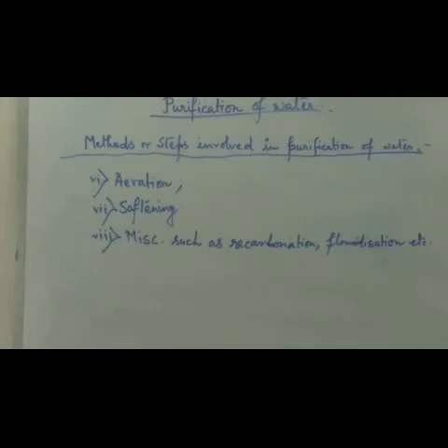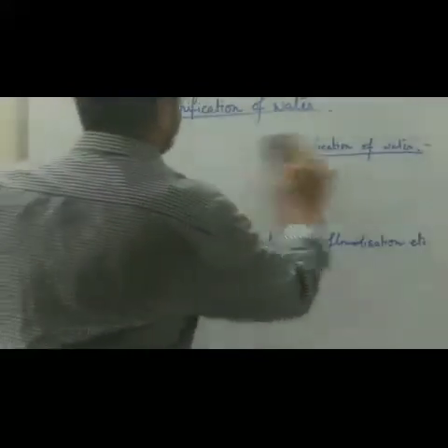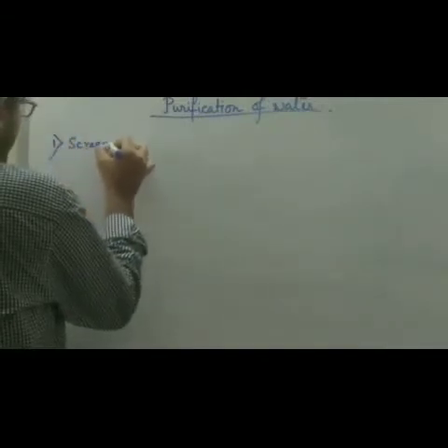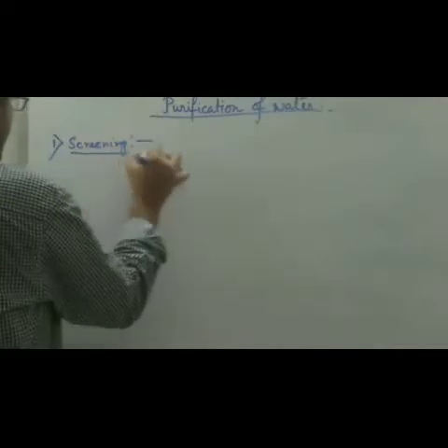So first of all we will discuss the first step, that is screening. So please write down the screening. The screens are generally provided in front of the pumps or the intakes of the weirs so as to exclude the large sized particles.